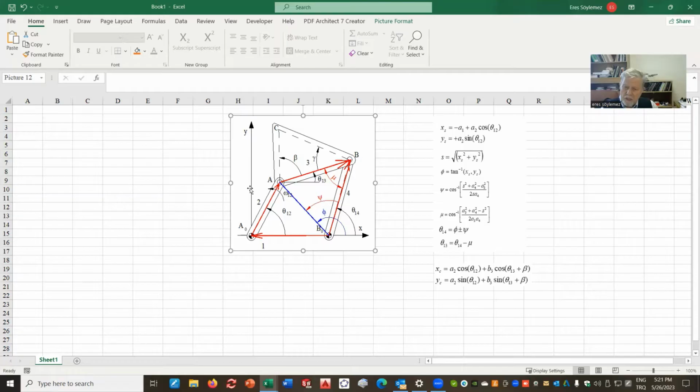So keep in mind, you can be in any one of the quadrants, so whenever you are writing your equations, you must think about that. This double argument inverse tangent for phi is quite important. Then once you solve xs, ys, and then s, you can determine phi.